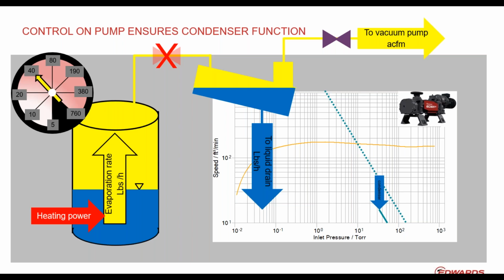If you have the control valve between reactor and condenser, as shown here crossed out with the red valve, your vacuum pump would actually pull, with this excess capacity that I was talking about earlier, vacuum on this condenser. That makes the condenser completely inefficient and absolutely impossible to condense anything at that state, again, pressure and temperature. So make sure your control valve is in the right place.